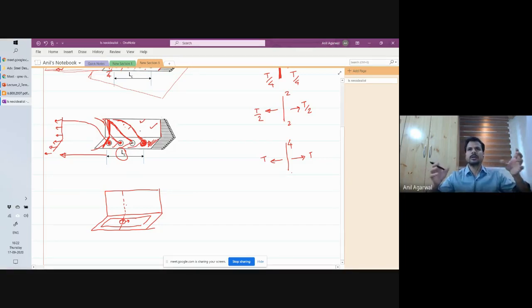If you have a joint with 2 bolts, you don't put them far away from each other. You try to put them close to each other. So either your LC is larger, or you have a large number of bolts in a series. Both of them reduce the shear lag effect.